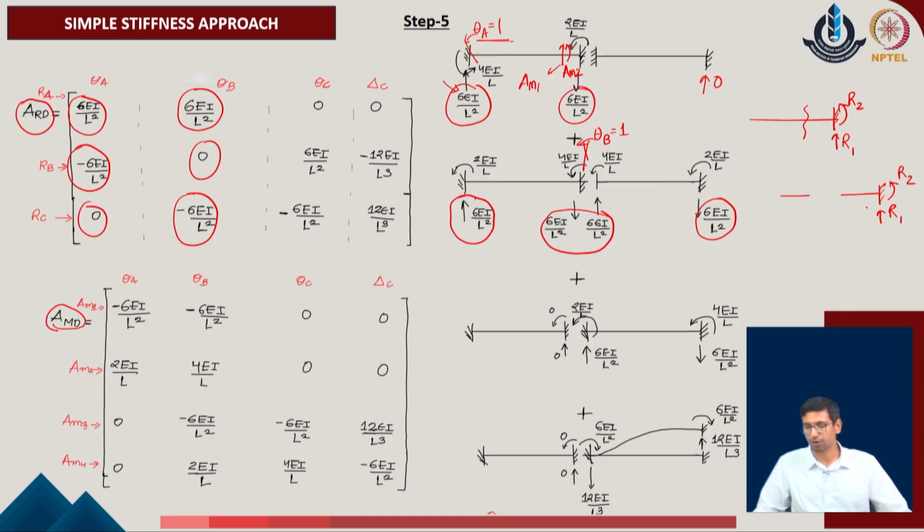So, this R1 and R2 will be fully balanced by the component over here, which is R1, and this opposite moment of R2. So, this is a cut which is made very close to the given end point. So, now in the second remaining component, the forces which will be translated will be in the same sign as the reactions of the given system were initially identified. So, in order to calculate the member forces, one can directly look at the directions of the support reactions and identify the same directions for the given member force component as well.